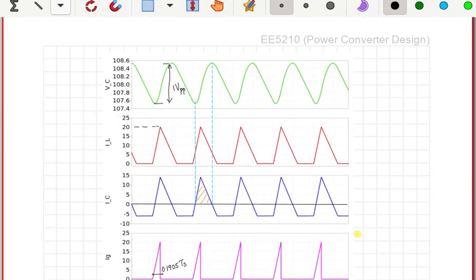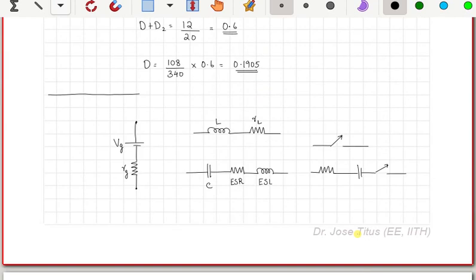It is not the final thing. So we always have a closed loop control for these types of converters, so that even if there is a small deviation from the desired output voltage because of these non-idealities, the closed loop control will usually adjust its duty ratio accordingly, and you will have the value of output as desired, right? But where these non-idealities affect you more is when you calculate the efficiency of the converter.